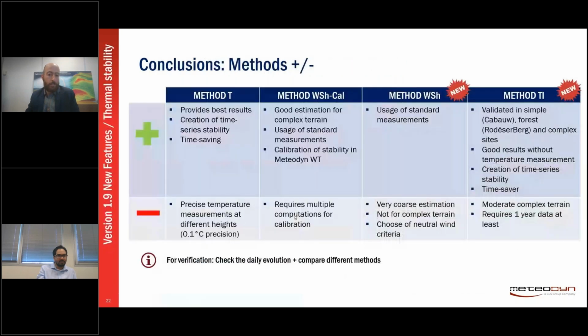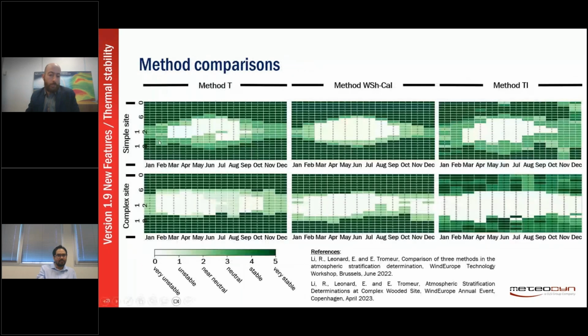So when we have these different tables, you see you can do one shear analysis with the hour of the day, and the seasonal variations. So we're providing one tool called WDA to get this shear analysis depending on the hour of the day, the months, and the sector. We can do it with WindoGrapher or other software, of course.